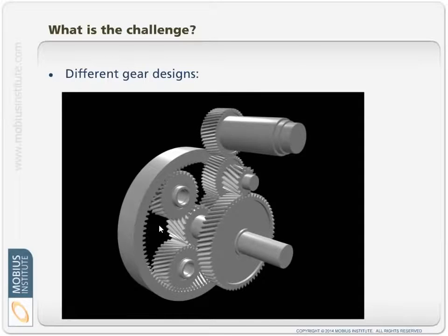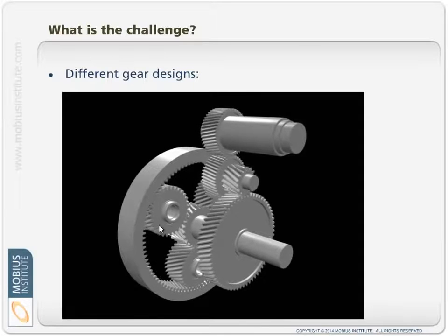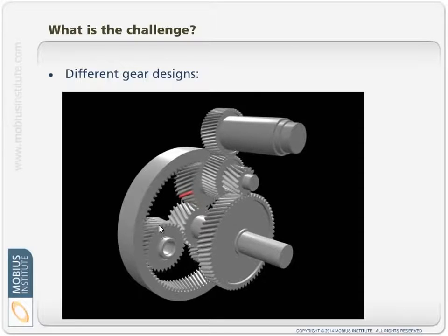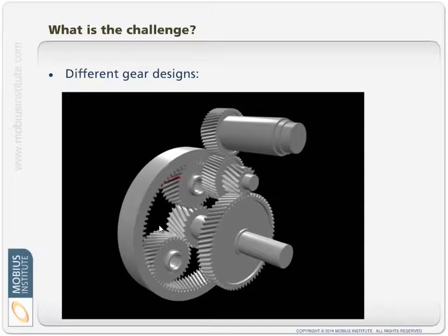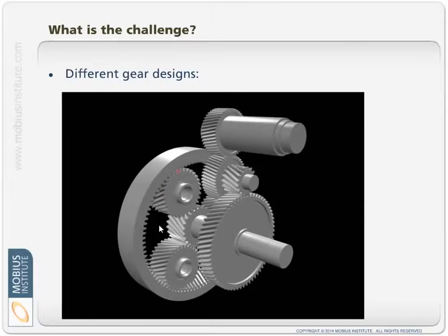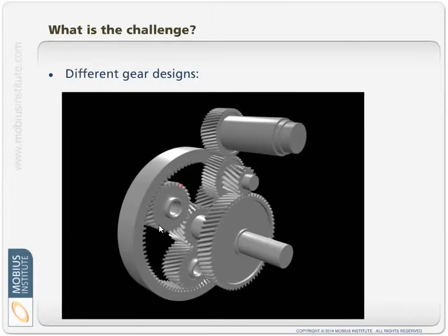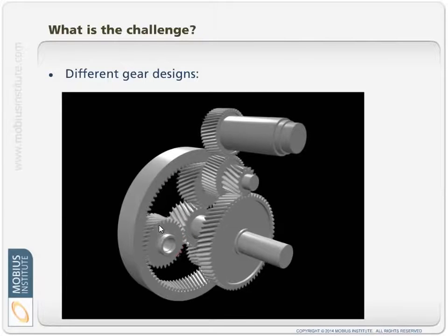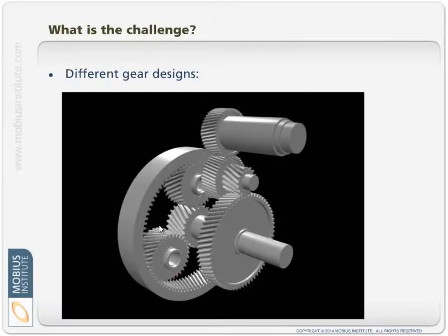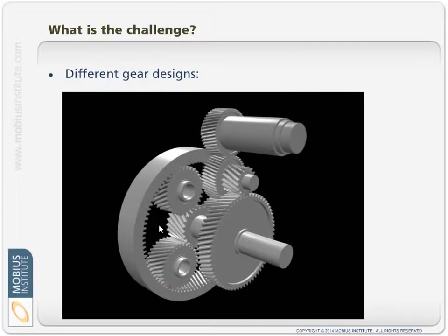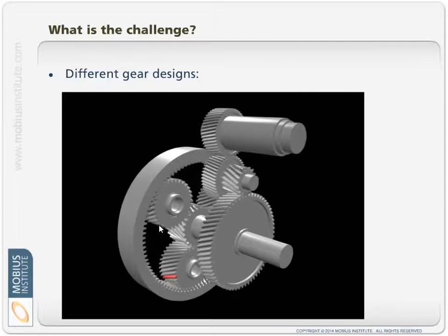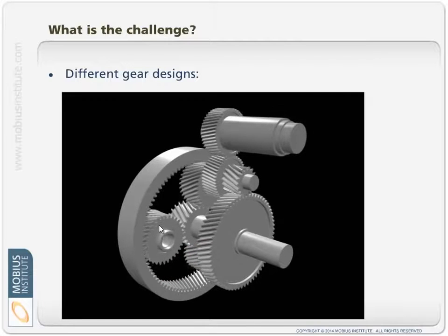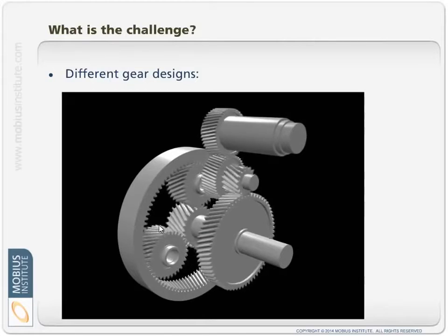You'd prefer not to, but in this particular instance with a planetary gearbox in a wind turbine, you may not be able to mount as many accelerometers as you might like. In a case like this, you are most likely going to be permanently mounting the accelerometers, and probably permanently monitoring the system as well. But if you understand the design, you understand all the issues related to detecting gear faults, then you can make the appropriate choices.